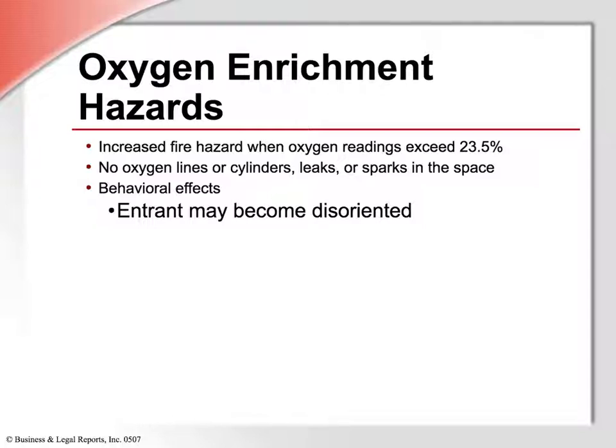In addition, atmospheres enriched with oxygen also permit flammable gases and vapors to ignite over a much wider range of concentration than possible in ordinary air. Care must be taken to ensure that oxygen lines and cylinders are not taken into the space and there are no oxygen leaks or potential sparks. Oxygen-enriched atmospheres may be created when workers use oxygen to ventilate a space or to power pneumatic hand tools under the mistaken belief that oxygen and air are the same thing. Fires under these conditions will burn with great speed and intensity.